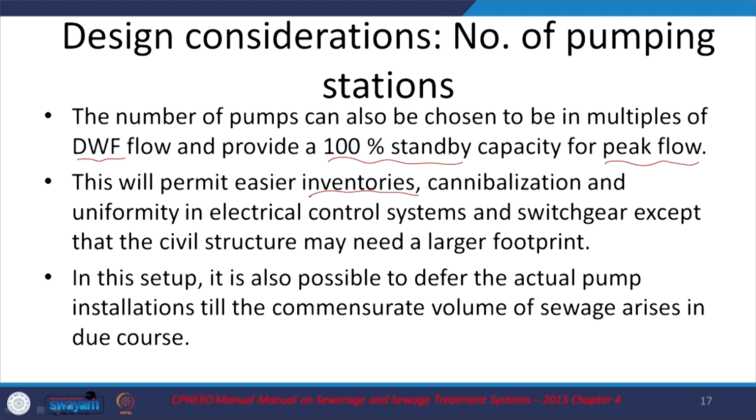And in this setup, it is possible that we do not need to put in the pump installation until the volume increases. I am designing my sewage treatment plant for a 30-year period. But right now the population is less, but that does not mean I should not start the sewage treatment. So, in this setup, you can keep increasing the capacity as and when the flow increases or is estimated to increase, rather than having all the capital spent right away and thus incurring costs. So, that is one aspect to keep in mind.